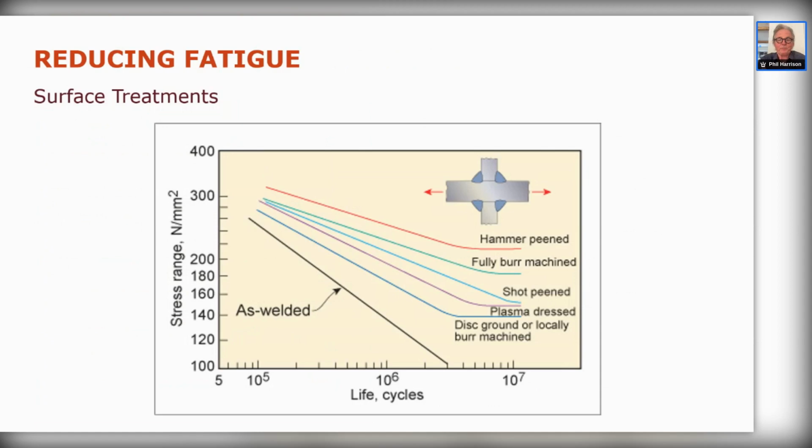And this is what we can do. Basically, you put a compressive stress in a surface. By hammering them, you get up to 60% of the yield stress as a compressive stress in a surface, depending on what you do. There's various methods of doing this. But, for example, as far as I'm aware, every valve spring on every automotive on Earth is shot peened.